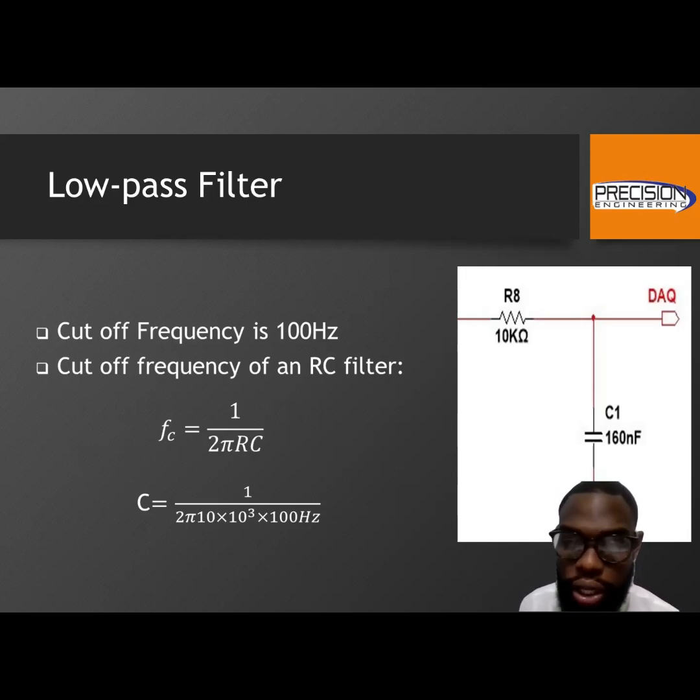It is also key to know that the strain gauge typically will be placed in the open environment. So there will be other things such as electrical noise, heavy machinery, motor vehicles, and things of this sort, things in nature, in the environment, that can and will contaminate the signal integrity. In order to prevent that, we utilize a low-pass filter.